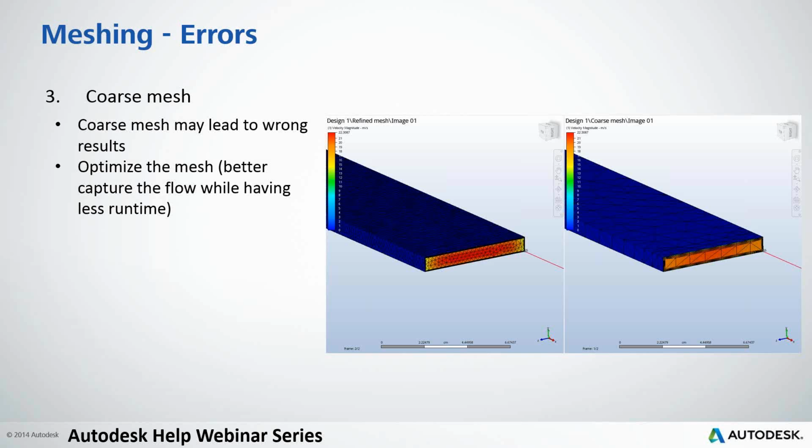I think there's a webinar with Royce, and one with John, talking about different meshing things. Just to give the brief overview, you want to make sure that you have a few nodes that aren't in the enhancement layers to be doing the calculations to have a good velocity calculation. We can see here also the difference: on the refined mesh the flow is well captured, not like on the coarse mesh where we can get really wrong results if we calculate the velocity or pressure there.